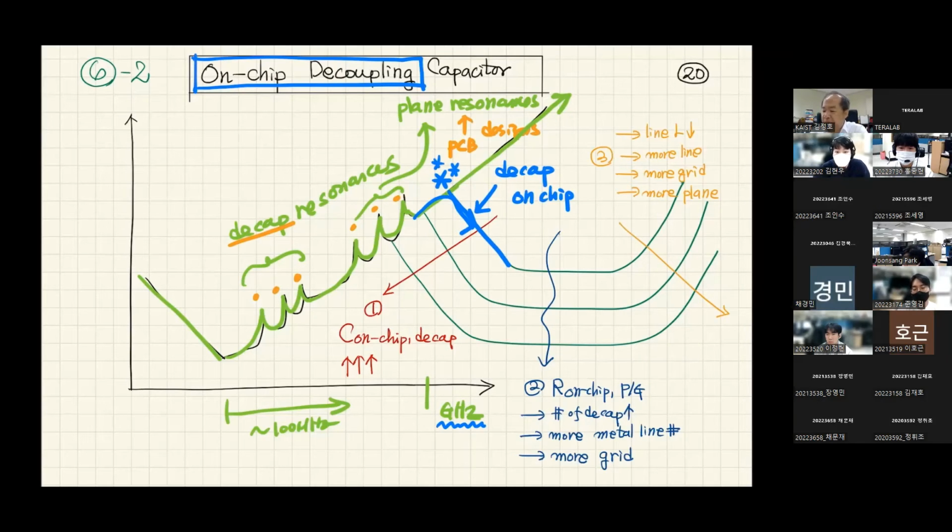They have inductance of PDN, and they have on-chip decap of their application processor for the Qualcomm chip. Is that Snapdragon? This frequency is about the gigahertz range, and in some applications, it may interfere with RF communication systems.